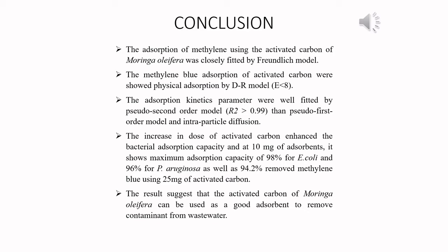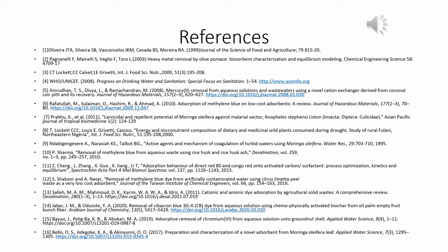The increase in dose of activated carbon enhanced the adsorption capacity, and at 10 milligram of adsorbent, it shows maximum adsorption capacity of 98% for E. coli, 96% for Pseudomonas, as well as 94.2% removed methylene blue using 25 milligram activated carbon. The results suggest that the activated carbon of Moringa oleifera can be used as a good adsorbent to remove contaminants from wastewater.